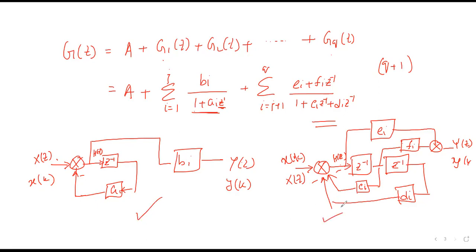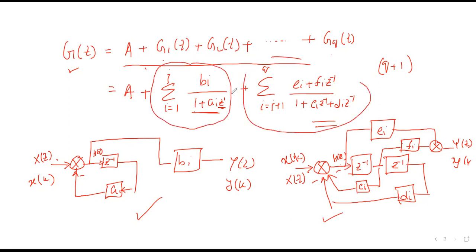So bottom line, the first thing you should do is whatever the pulse transfer function is given, you organize that as a combination of partial fraction expansions like this, and then try to distribute them in terms of few first order and few second order pulse transfer functions. In this way, the quantization error of your A I s and B I s can be minimized a bit.